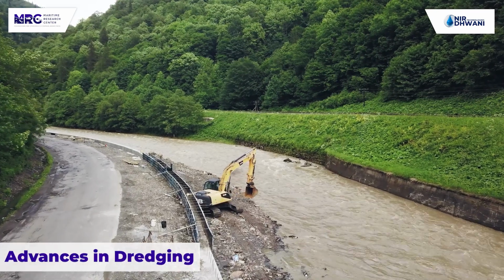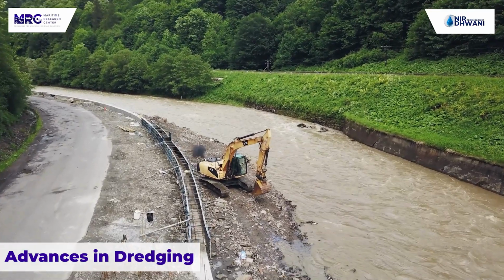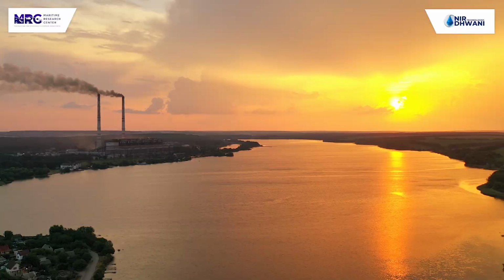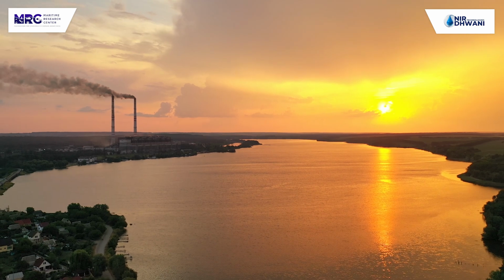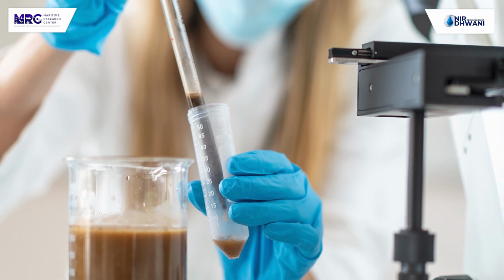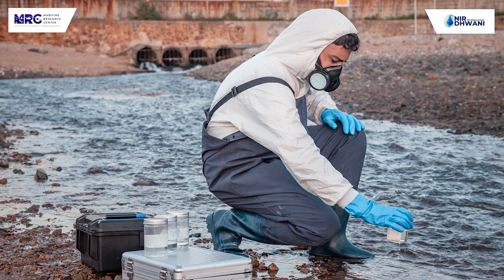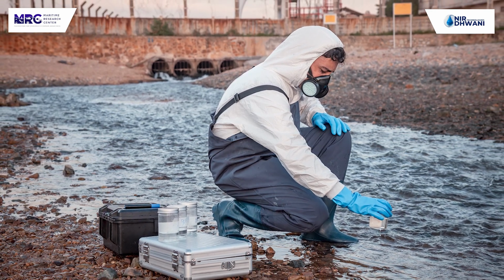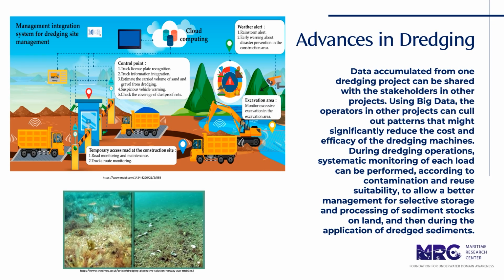During the dredging operation, systematic monitoring of each load can be performed according to the contamination of the sediments and reuse suitability, which would allow for a better management of the selective storage and processing of the sediment stocks. The environmental impact of these dredging operations can also be better monitored by having an on-site real-time analysis, especially for the water, like the turbidity and the contaminants, rather than having a laboratory analysis on the various discrete samples that are being pulled out. On-site analysis allows more closely spaced and more frequent analysis than sampling and laboratory analysis, which would allow for a quicker feedback and are better understood by the communities and the various authorities.